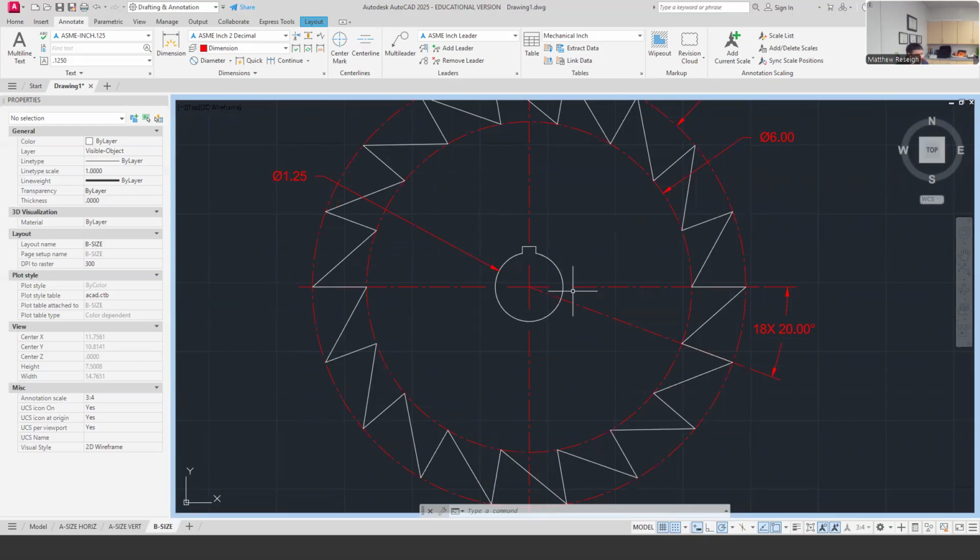Generally, what someone knows when they cut a keyway or key seat is they know the shaft diameters. That's what really drives the sizing of the key, knowing how big the shaft is that I'm matching. Then the key, the keyway, and the key seat can all be cut knowing what the diameters are. And what drives the diameter? Well, that's your engineering.